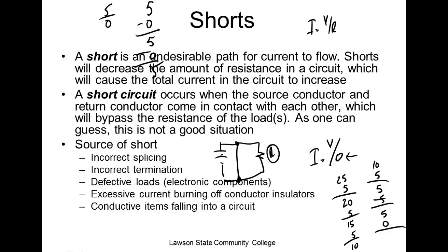Now, if I've got a little AA battery and a AAA battery and I put a little wire across it and short it out, if you put a voltmeter across the battery, the output of the battery would drop to 0 because the internal resistance of the battery is dropping the voltage. If I go out to my car alternator, which is a regulated power supply, which means if the resistance goes down, it automatically raises the voltage, and you short out that sucker, you're going to be in big trouble if you don't have a fuse. So there is a fuse in your alternator lead. So somebody's going to give up, right? You understand? If we have a short circuit, somebody gives up. Either the voltage source gives up or the conductors give up.